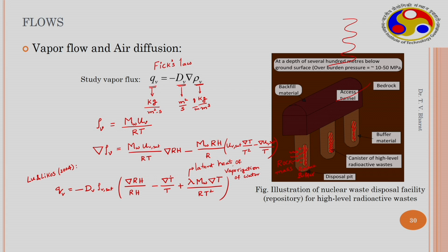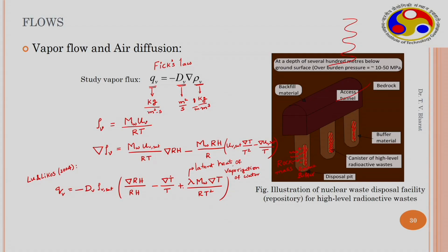Generally, the coupled phenomena need to be solved because there is vapor flow, there is heat conduction taking place, there is water flow that is taking place, and the bentonite exerts pressure on the surroundings, that is a mechanical pressure that is exerted. So, hydro-thermo-mechanical studies are often conducted by coupling all these analyses together. In this particular case this is very important. However, as this course is for a preliminary audience, these advanced issues are not discussed in this particular course.